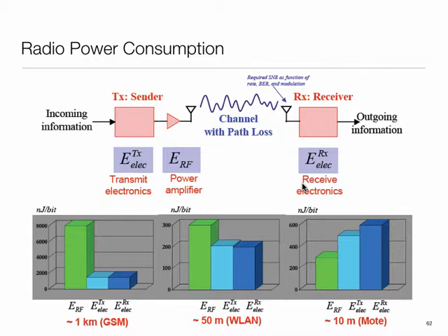So same thing with the radio, it has an architectural advantage. But by the time you hit cellular, distances are so much that that's what dominates. So it's not uncommon to find that for bulk data transfer, your Wi-Fi may actually consume fewer joules per bit than a short-range radio. But where the short-range radio excels is if I have to send a bit infrequently. Okay, so I send it, go to sleep, send it, go to sleep, then this guy will excel. We'll talk about it later.